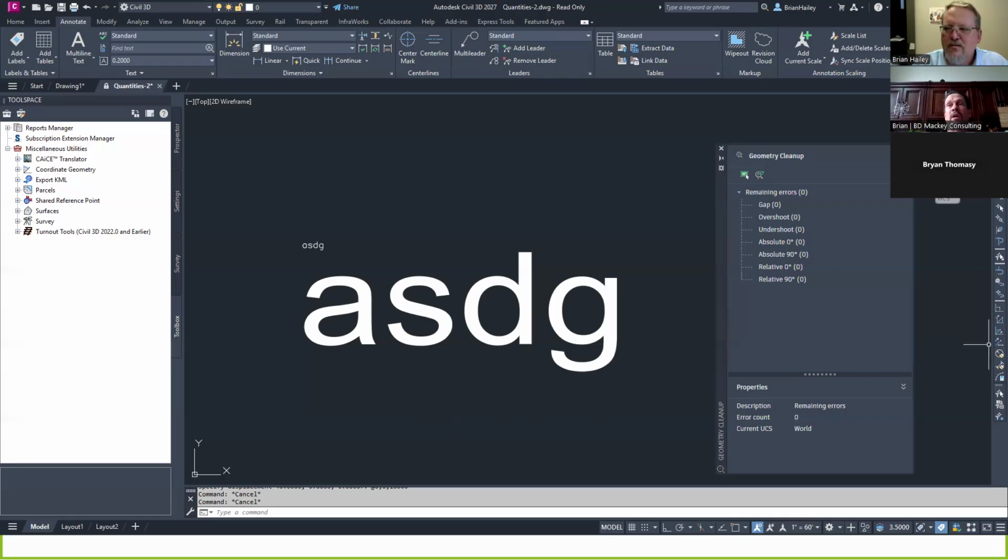The other thing that's really weird is your SHX fonts, like Haley said, going into PDF, but you can also have issues with PDF fonts as well. Every time you convert something, especially if you're using Bluebeam, it has its own version of the Arial font or its own version of the Calibri font, and you can actually have corruptions in there. I've seen people who've customized the Arial font to have custom symbols in there, whatever they wanted, but then when they print it, it's not printing properly to PDF because you're customizing the Windows version of it, not the PDF version of it. Just stick with common simple fonts.